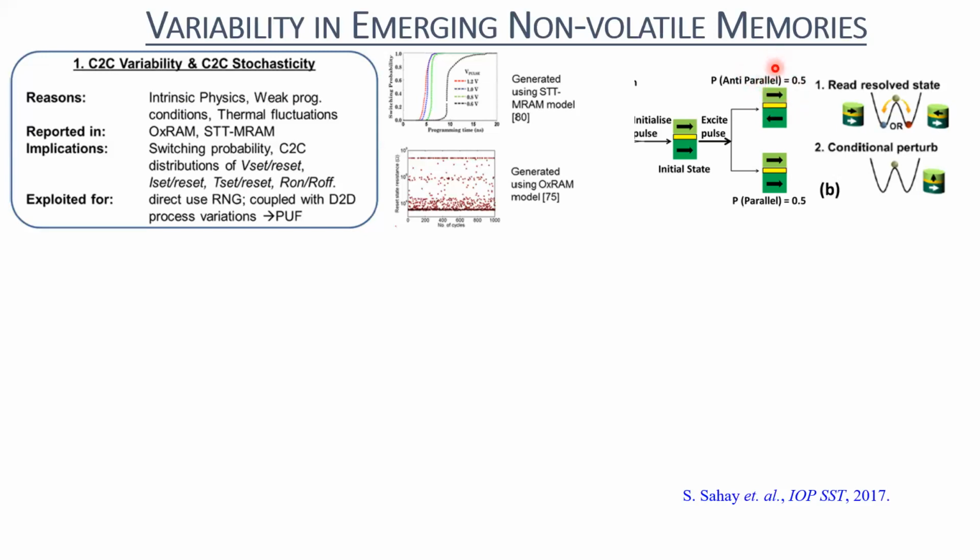So the charged electrons which are coming from the battery enter this ferromagnetic layer. Here they experience a spin transfer torque. That torque tries to align their spin along the direction of this spin layer. And then through this tunnel layer, they flow into this layer. Once those electrons flow into this layer, since the number of electrons flowing in is huge, and since this is not a pinned layer but a free layer, those electrons are polarized in this direction, having magnetic moments in this direction. So once they reach this free layer, those electrons exert a spin orbit torque, sorry, not spin orbit torque, that's an entirely different concept.